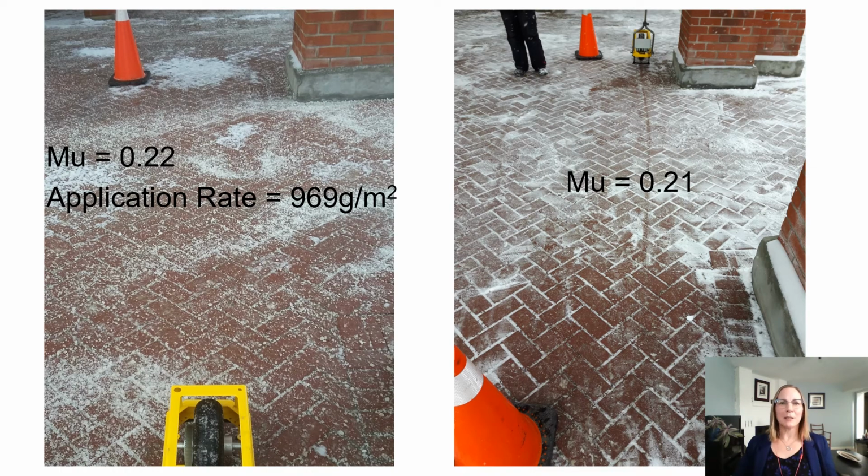The picture isn't totally clear though. The photo on the left shows an oversalted walkway with a friction value of 0.22. The application rate is almost a kilogram per meter squared. And then the same walkway has the snow shoveled off it on the right, but no salt applied, and it has a very similar value at 0.21. To increase the friction and make this surface safer, the contractor would need to apply some salt according to the weather and traffic conditions. So the friction testing has provided some information, but it's not as cut and dry as we were hoping. We're going to continue to work on this and are hoping to get some more real-time measurements with our contractors and refine the messaging around the proper use of salt.